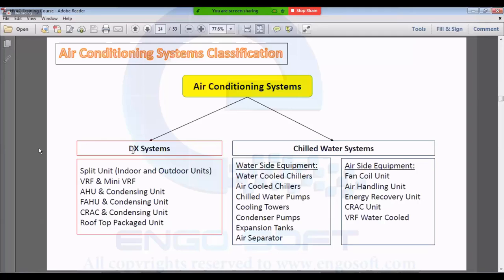Okay, air handling unit: if you want to cool a space, you provide a supply duct and a return duct. The AHU contains a supply duct where you provide all the flow needed by the space, and a return duct where you return to the equipment around 70%, 80% of the flow.